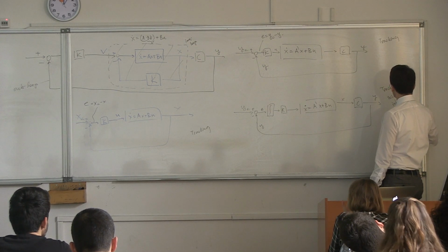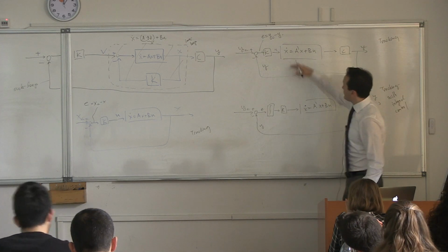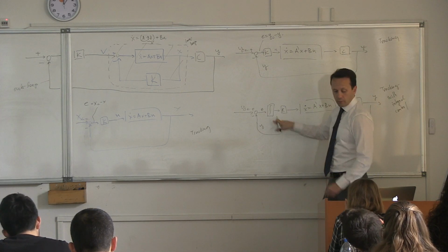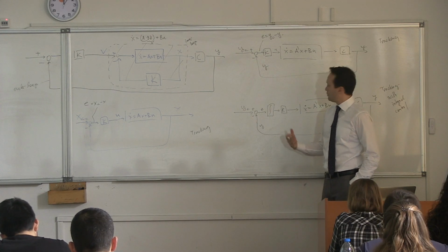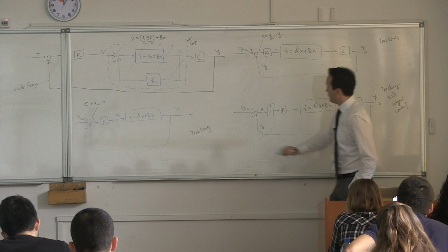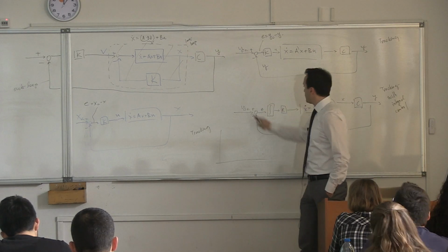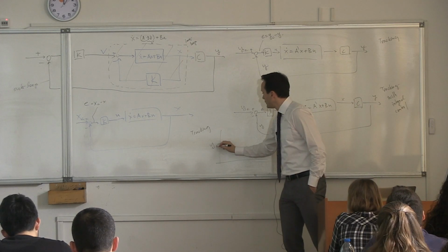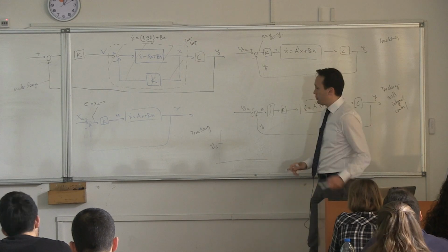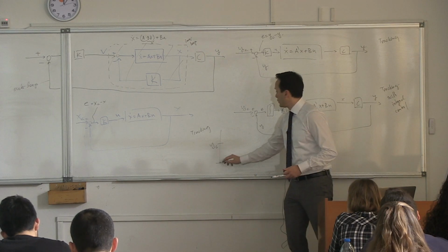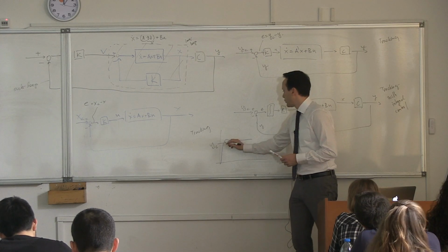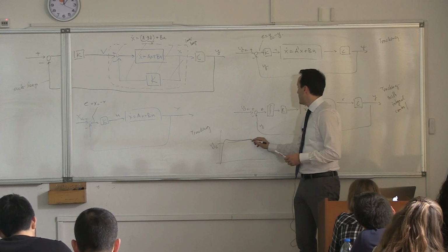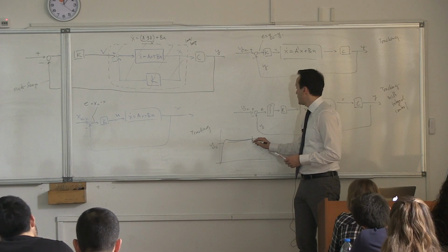Integral control. So the difference between this and this is the integral over here, of course. So why would it be different in practice? In practice, it would simply be different because if you had a yc command, right, the response would probably look something like that. If you design it right, of course. And you would, at the end, have 0 steady state error.